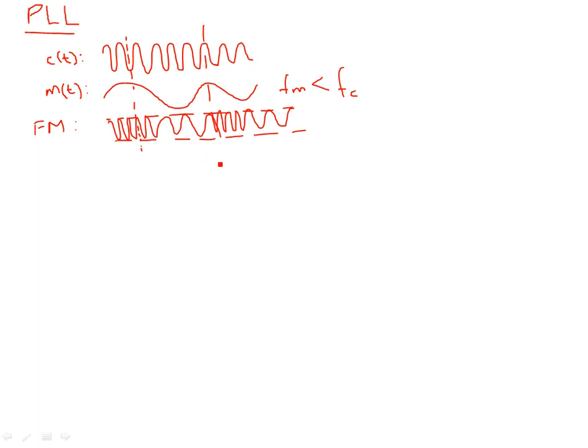So what this graphic shows is the instantaneous FM frequency, let's call this fi, around my carrier frequency FC. Note that there's no change in the amplitude of the FM signal. So FC is being varied with respect to the message signal, and KF, you can say, is the sensitivity of the FM modulator. Okay, so it's just like a proportionality constant.